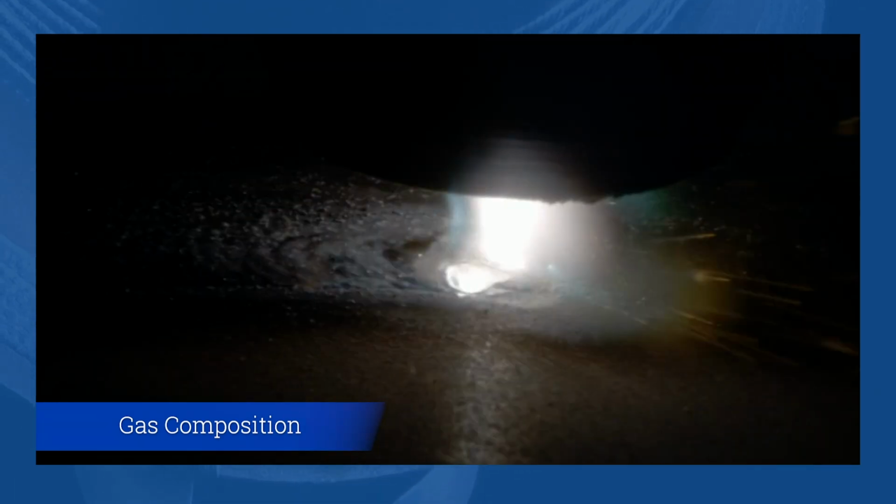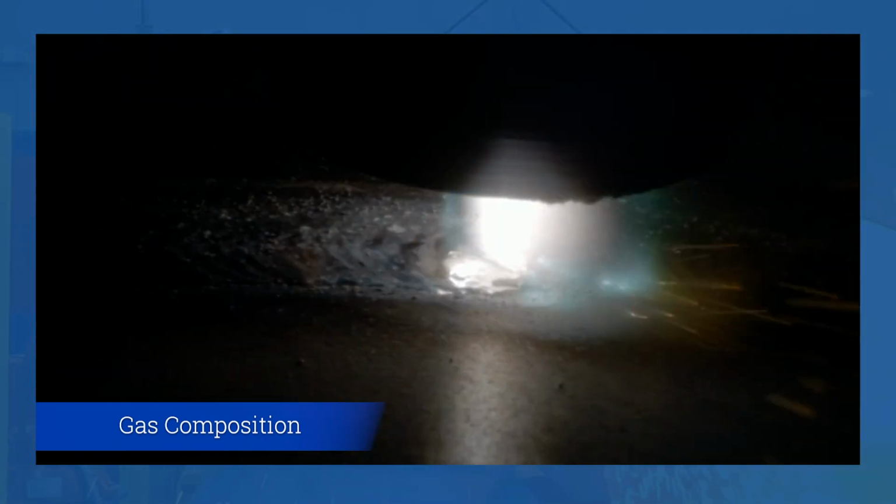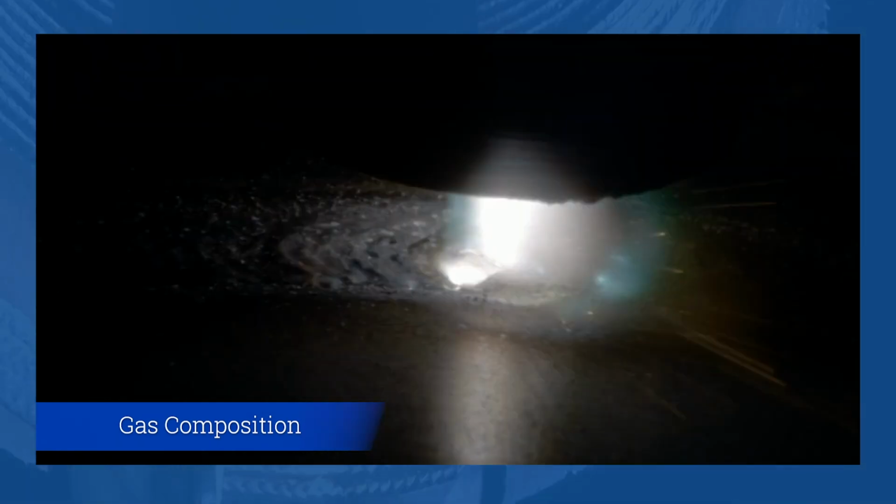The way we do it is we try to add a little bit of hydrogen, around 5%, to the shielding gas, and you can see it does magic things. It allows that weld to wet and flow because we're reducing the oxides with a gas rather than heat. So this really isn't a variable that you would change in production.